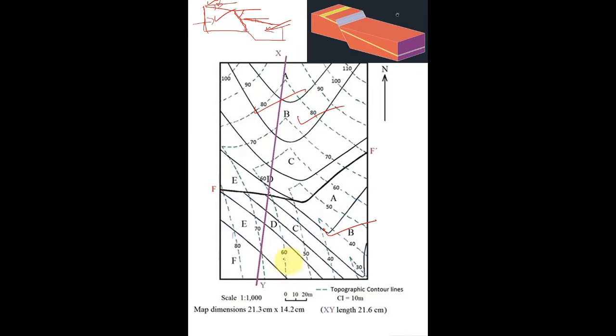We'll be drawing strike lines for the lower part, and we'll also be drawing strike lines for the fault line. Okay, so let us start by marking those points. First, I am taking this AB junction. In the AB junction, as you can see, this contour line of 90 is cutting once here, and the second one it is cutting here, right?